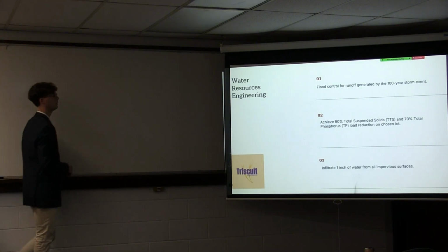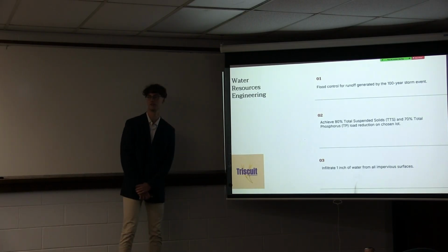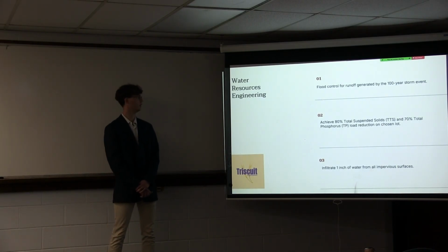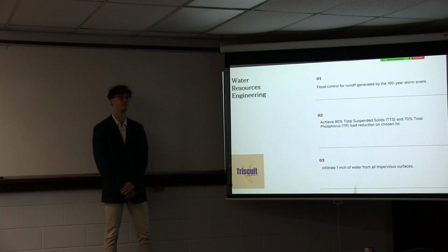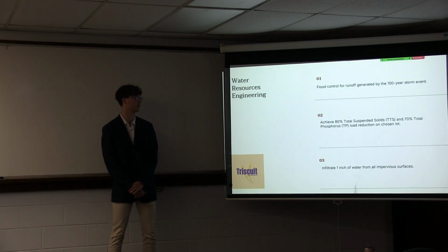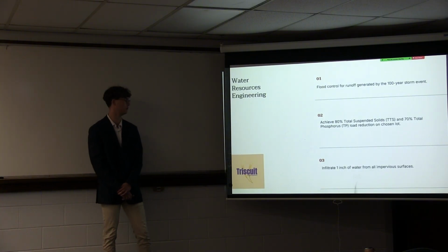Thank you. Okay, so my client specified that we need to create a flood control plan for the 100-year storm event, achieve 80% total suspended solids and 70% total phosphorus removal, and infiltrate 1 inch of water from all impervious surfaces.